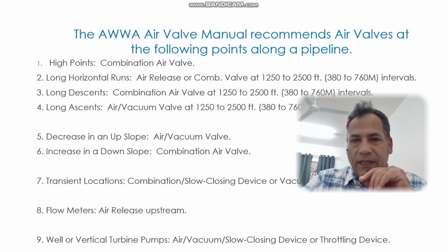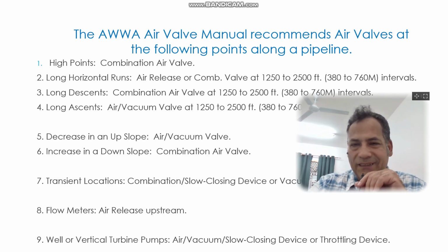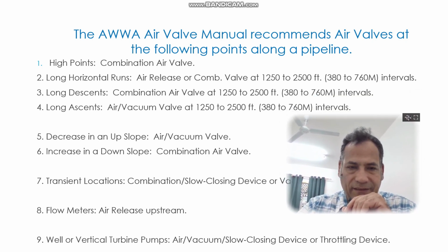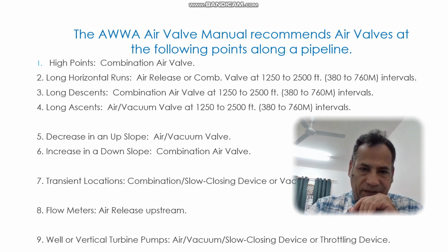The AWWA air valve manual recommends air valves at the following points along a pipeline. High points, combination air valve. I explained all of those points, and which type of air valve for each.